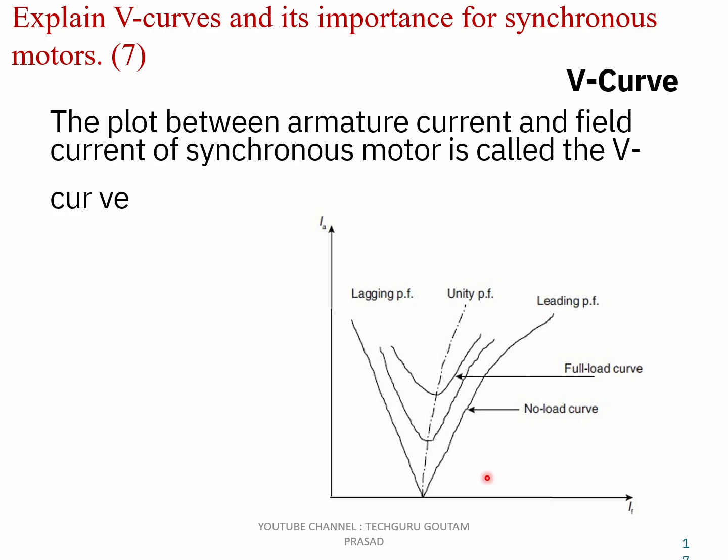So this is a very unique kind of motor that is capable of operating in all the three power factor zones: unity power factor, lagging power factor, and leading power factor. This bottommost curve is the no load curve. This middle one is for a medium level of load, and this topmost curve is for the full load curve.